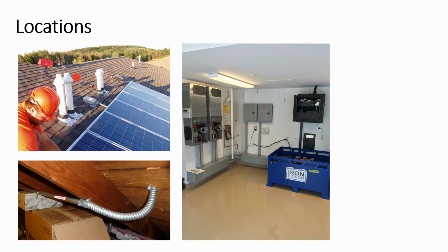And so the question is, well, how do we do that? We put a fitting in the roof cap that we could land the conduit on at this point of entry. Your fitting may have one big hole in it. Let me pull up my pen so I can illustrate this a bit better. What we had is a Z purlin. So here is the roof cap, and here is the bottom of this kind of standing seam rooftop. The roof went over it, and there's this little shield that gets installed, and we put a hole in that shield to route our conduit into the hole.